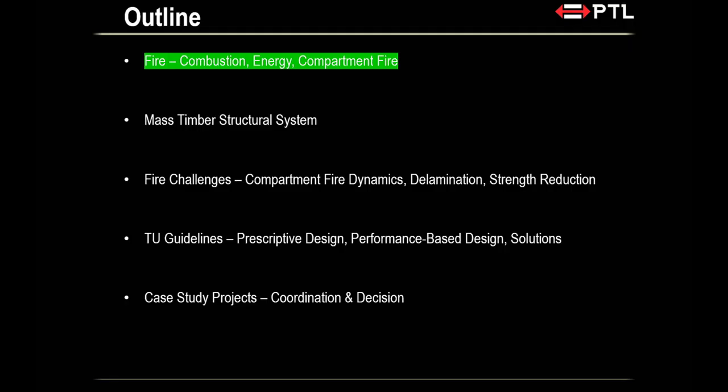So there are a few components in here. I'm going to talk a little bit about compartment fire dynamics. You wonder why? Because that's what drives a lot of our design calculations and also assumptions, eventually arriving at a char depth, which is a parameter that you will be using when you're designing your structural system for fire. When it comes to mass timber, I'm concerned about delamination.